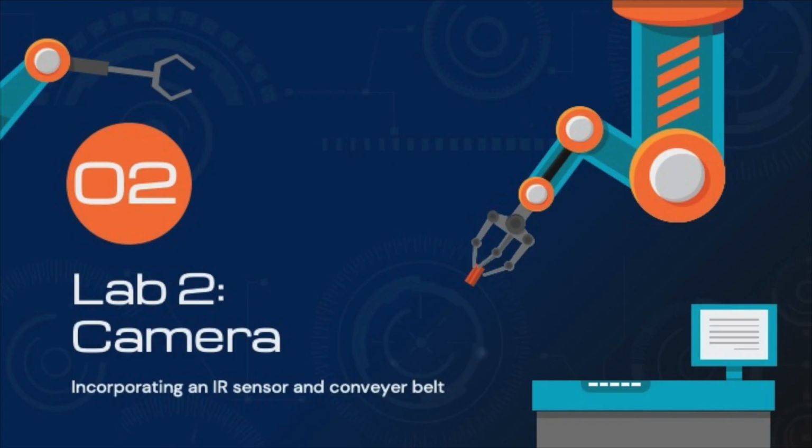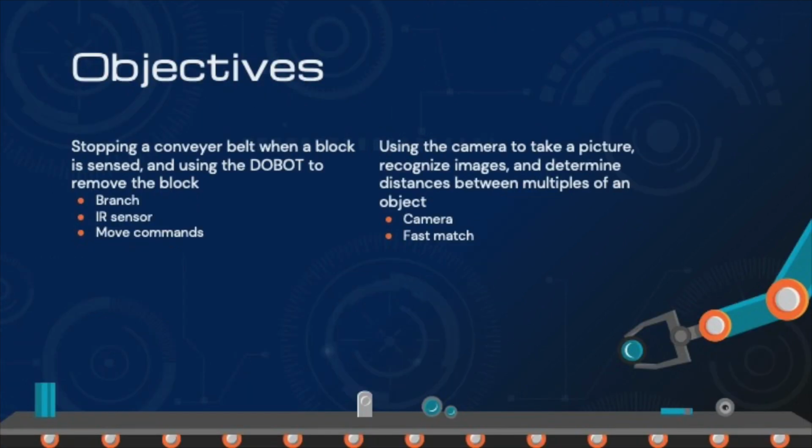For Lab 2, we stepped up the complexity of our robot's movements by a lot, this time by incorporating a conveyor belt with an IR sensor. Our team was tasked to learn how to set up flows so that when a colored block was in front of the IR sensor, the conveyor belt would stop and wait until the block was removed.